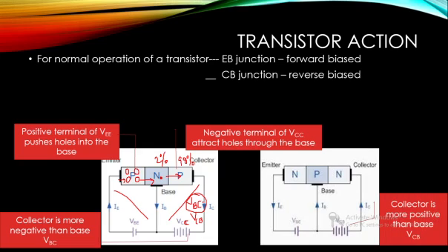While in the case of an NPN transistor, the potential difference will be represented as VCB, because here both collector and base are connected to the positive. So we represent the first letter as the one with more positive. Which is having more positive? Yeah, collector is having more positivity. So C denotes collector, followed by B. So that is how a voltage drop, or potential difference, is mentioned.